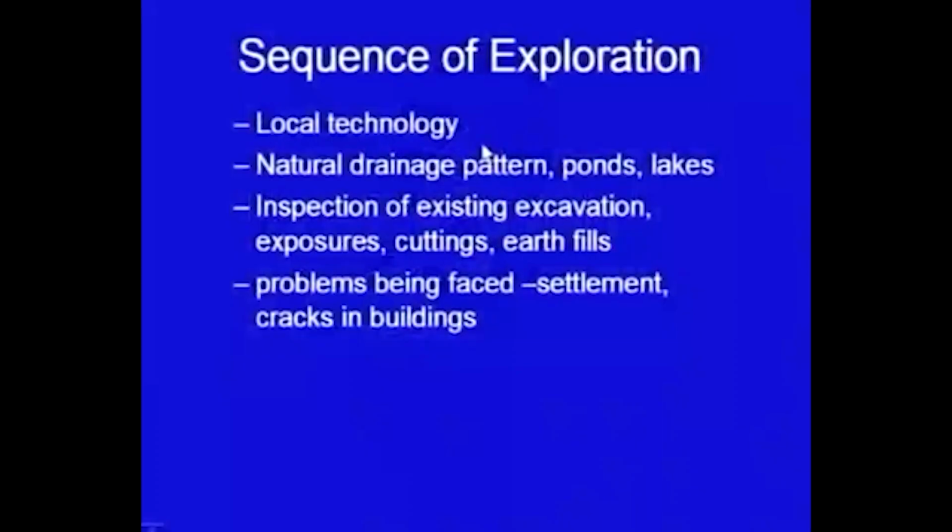Also, look into the local technology, sometimes very useful things are available. What is the natural drainage pattern at that particular site, whether it was a pond, whether it was a lake. Many a times you will be having a site which in pre-history period there might have been some pond there, there might have been some lake or something like that, there may be filled up soil.